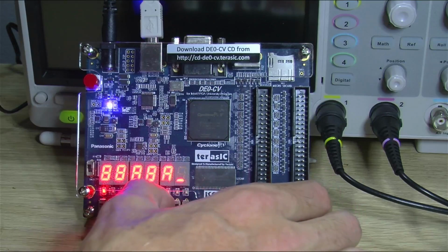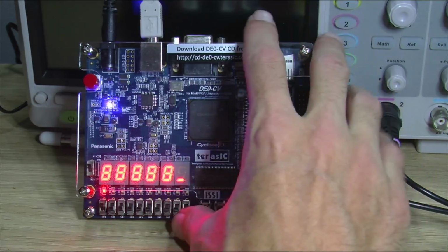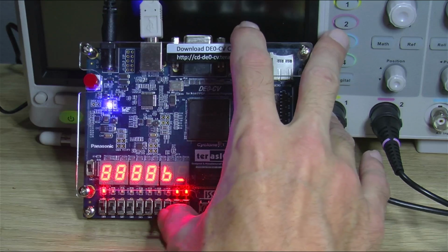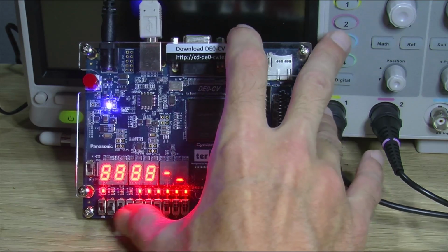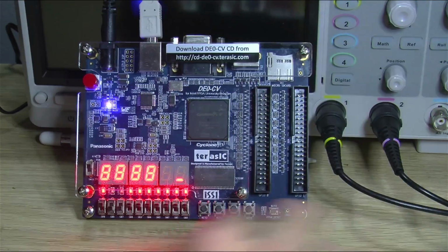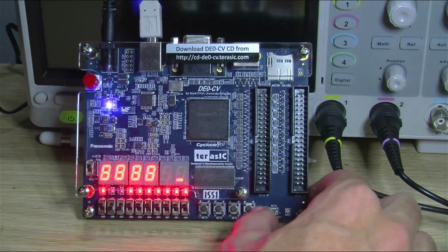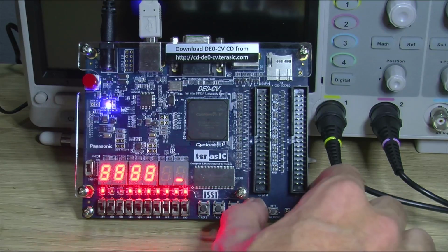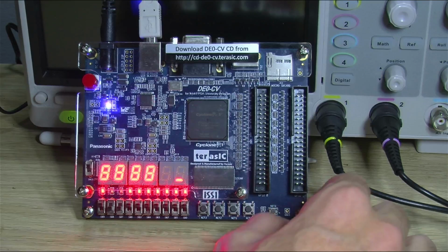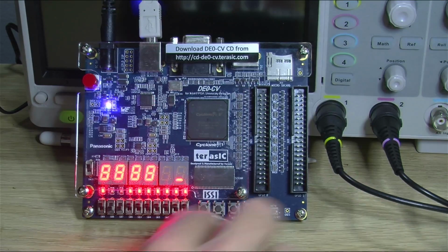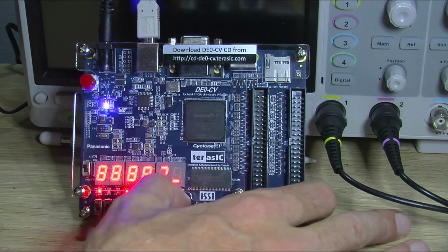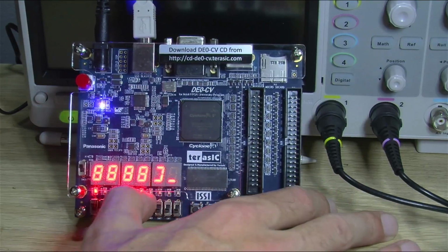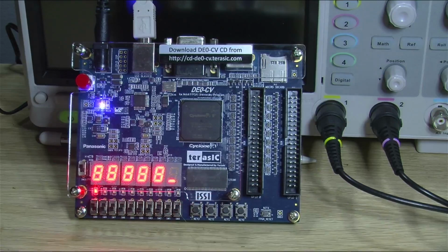We turn all of the switches off, all of those segments light up, and then as we turn each of those off in turn, we'll also be turning off each of the segments on the display, and that's separate to the functionality that we put in there with our button where it inverts the LEDs. So the LEDs are doing stuff separately to what the 7-segment display is, even though they're both hooked up to the switches. So again, quite a bit of flexibility in how we go about getting things to work inside the FPGA. So that is what an FPGA is.